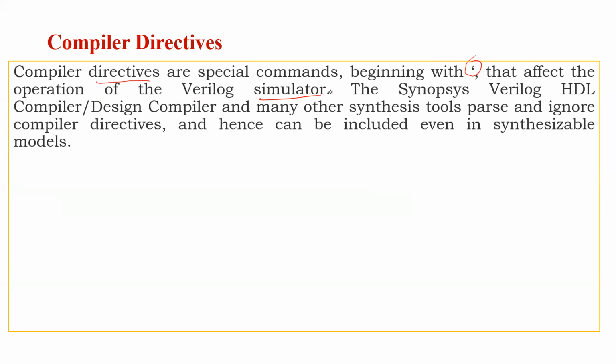The Synopsys Verilog HDL compiler, Design Compiler, and many other synthesis tools parse and ignore compiler directives. They can be included even in synthesizable models.